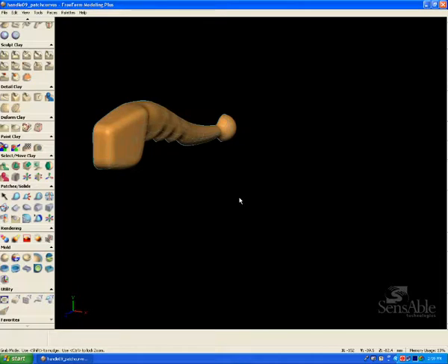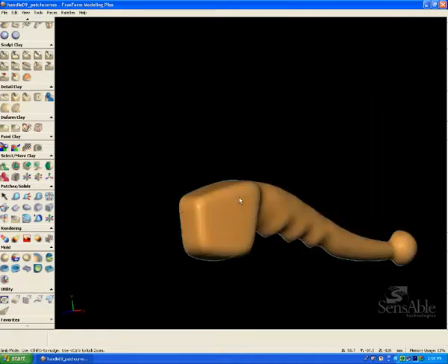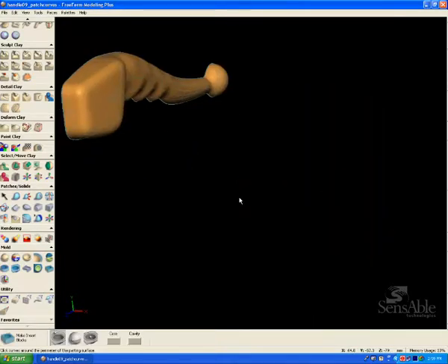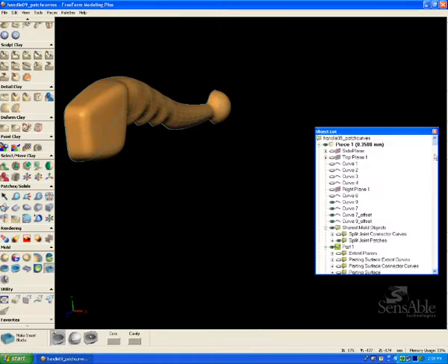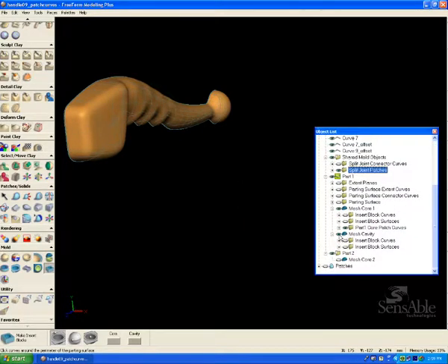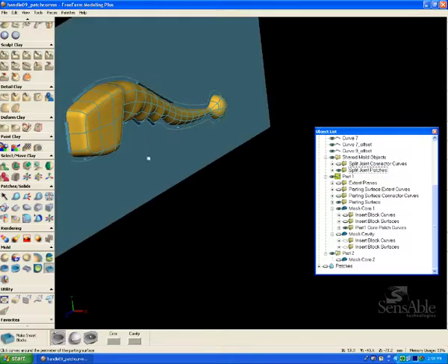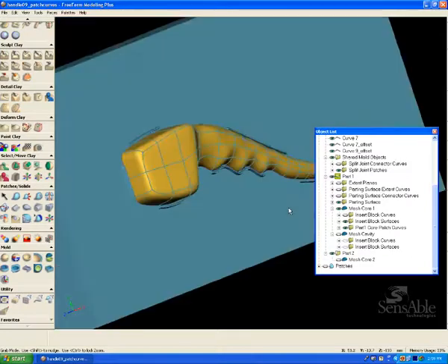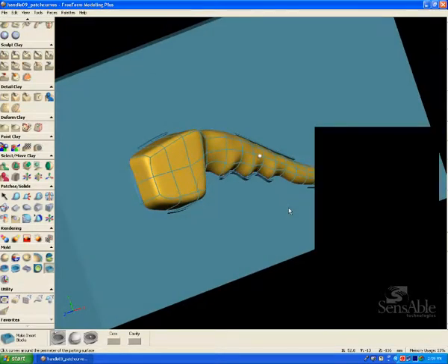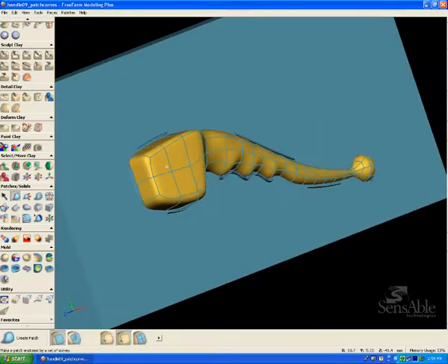So what I just did there is I showed you, I started drawing some fit curves along the mesh, and since it does take quite a bit of time for the demo, I just opened up the next file where all the curves were drawn and completed. So you can see that I've set up a network of curves along that side of the handle. So at this point I want to go ahead and start creating my manual patches along this entire piece using these curve networks.